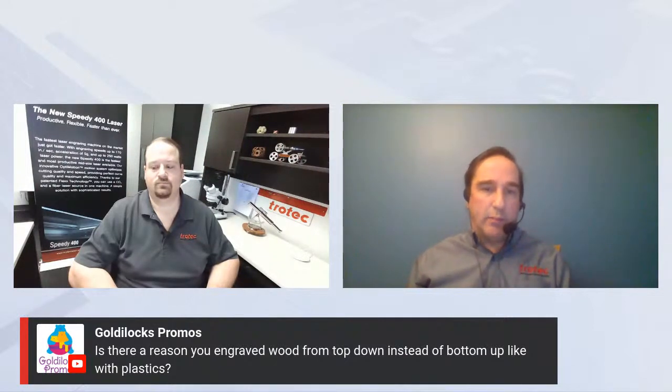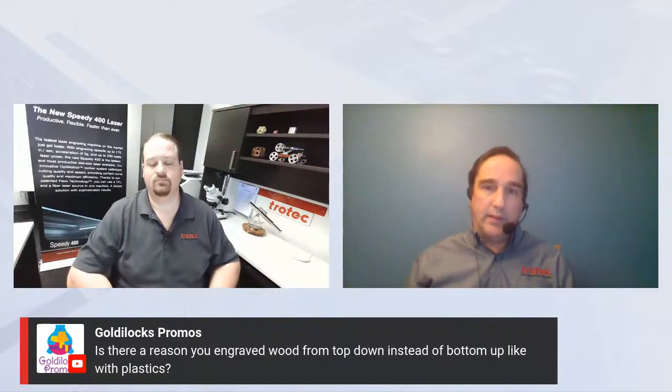In my experience, you can sometimes play with it for different effects too, because the reason you're doing the bottom up is so that the exhaust isn't pulling the dust and everything back into what you've already engraved. So you're basically always engraving on virgin material, not engraving through dust. With wood, because it's the resin and smoke that gives you the color, sometimes you get a better look doing top down, because you're intentionally having that resin and smoke go across your engraving.